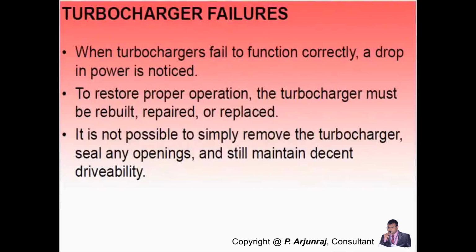Is the wastegate only for a conventional turbo? So I told you the main purpose of this wastegate is to avoid overboosting. Okay, there is a possibility that the conventional turbo we are using also has some issues compared with the variable geometry turbo. Even considering the turbo lag and whining noise, we are using the wastegate where the requirement of boost pressure control is very much important.